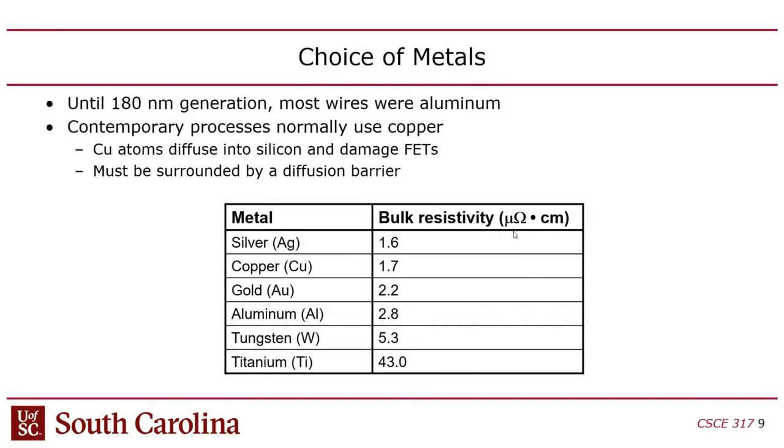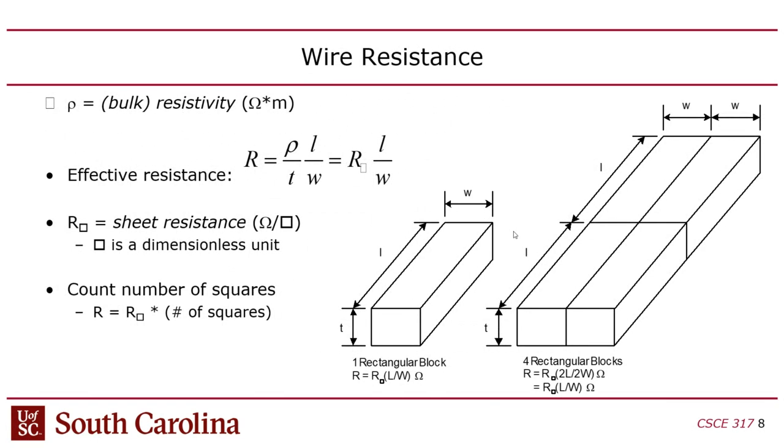So almost twice as conductive. And resistance translates directly to speed, right? I mean, because the delay is RC, so obviously the more you can push the resistance down, the faster the chip is, the faster the propagation delay goes down, the faster you can run the clock.